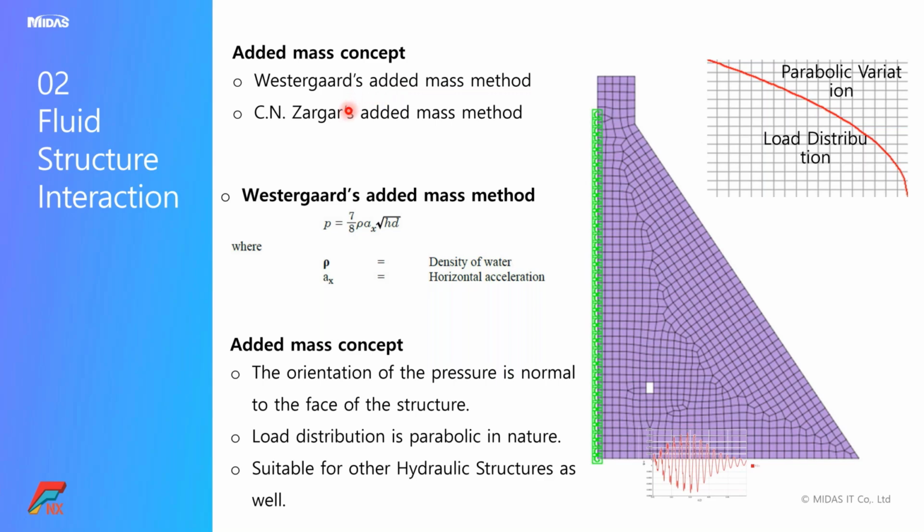In the case of the added mass concept, we have two options: Westergaard's added mass concept, and the other one is Chopra's added mass concept. In this particular analysis, we have considered the Westergaard method, wherein this is the equation that is considered to calculate the forces acting on the face of the dam. And the major properties of this Westergaard concept are as follows.